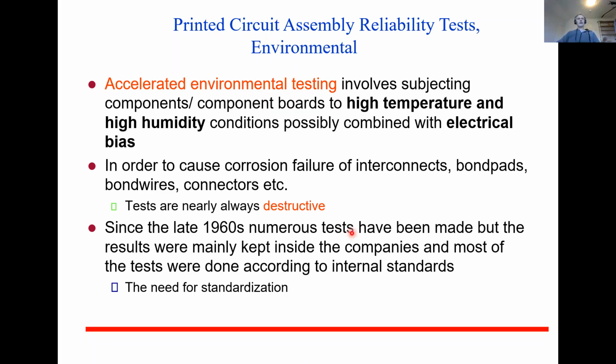And on the other hand, if one thinks about the most commonly used reliability tests during the last 50 years, 60 years, they are either thermal cycling or temperature and humidity. So there's a huge amount of different types of combinations of temperature humidity tests developed during the last decades.